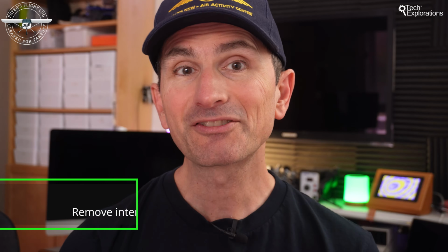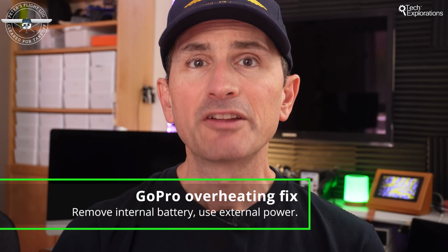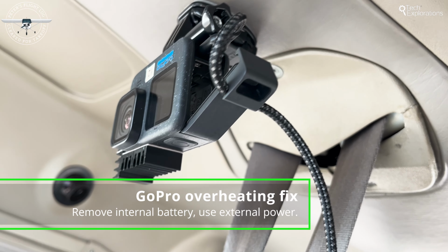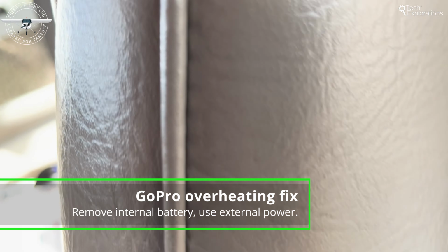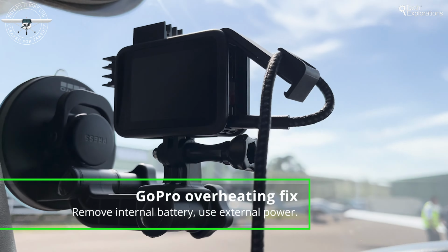I finally solved the problem with my GoPros switching off due to overheating. The solution is to use an external battery. This removes the internal battery, leaving the battery compartment empty. By leaving the battery door open, the airflow allows for better heat exchange between the camera and the air around it. This adds to the effect that the heat sinks already have.